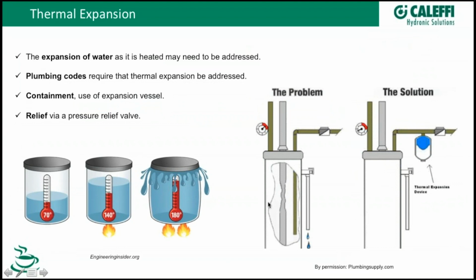So if you have a water heater, and I'm assuming you do, or you should have one, they're kind of nice to have. What's going to happen is when you put water in this vessel and you heat it up, it's going to expand. Now, most of the time, this water could just expand and push its way back into the water main, and you don't notice an increase in pressure on a gauge or in the tank. What's happening more and more often is we're seeing backflow preventers on buildings, either out in the water meter pit or somewhere inside the building. The local jurisdiction might require that for protection on their water mains.